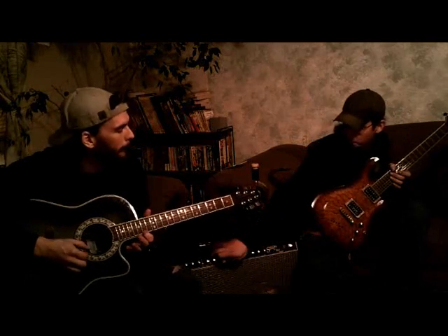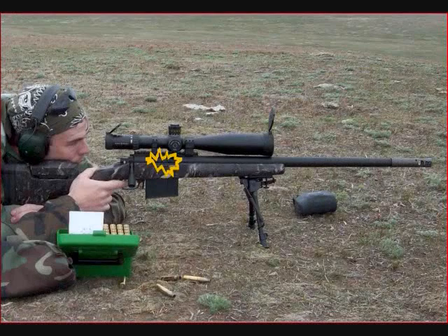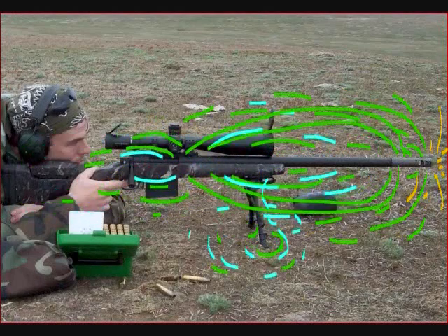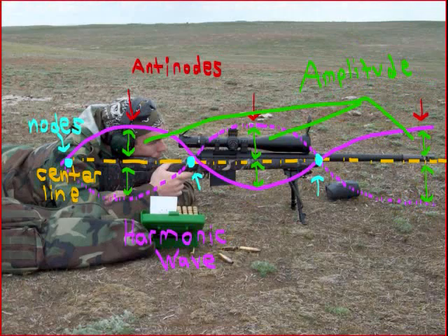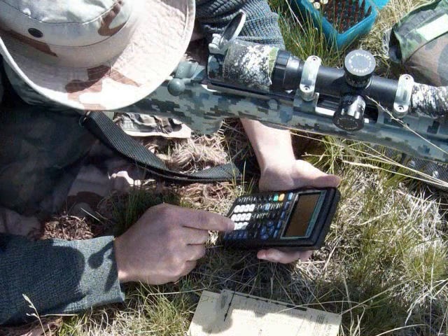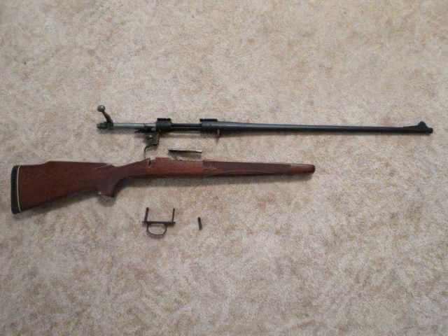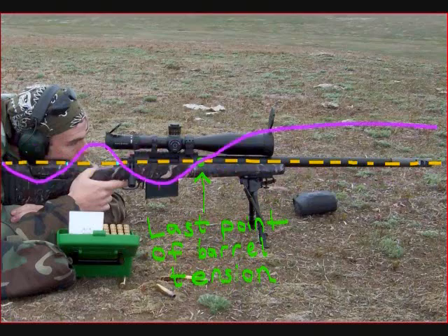If you have 3 shots in a row where you have the same exact tune ringing down the barrel, and then on that 4th shot, you kind of touch it halfway down the barrel, it's going to put a damper on the harmonic vibration, and that can totally change the axis of your bore at the time the bullet leaves the barrel, and that can throw off your point of impact dramatically. So what you want is a consistent relationship between the barrel and the stock, and there's 2 ways to accomplish that. And basically, the one way, and we talked about this briefly in our harmonics video earlier, you can introduce points of tension that are solid points of tension along the barrel.